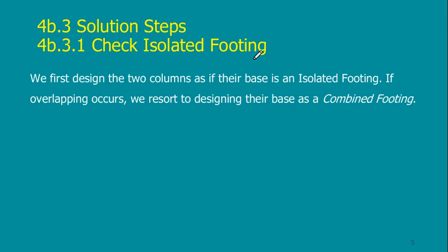And I get the plan of the other footing because maybe the columns are not equally loaded. They may be different in loads, so they will be different in dimensions also. And then I check, is there a possibility that I may change the dimensions of the footing so that they won't touch each other? Maybe I would increase the width in the perpendicular direction.